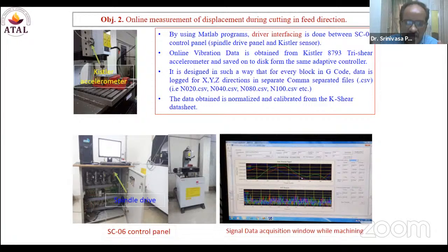And I'm suggesting vibrations because vibration signals are easy to quantify. There are many applications available in vibration signal analysis, though not in the field of machining. You can take the literature of vibration signal analysis in heavy machinery, turbines, blast furnaces, generators, motors, etc. The same logic can be applied here. Where there is a rotating member, you can apply vibrations. In milling and drilling, the rotating member is the cutter. In turning, the rotating member is the workpiece.